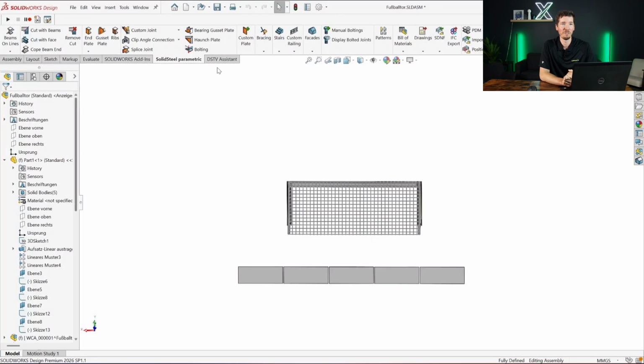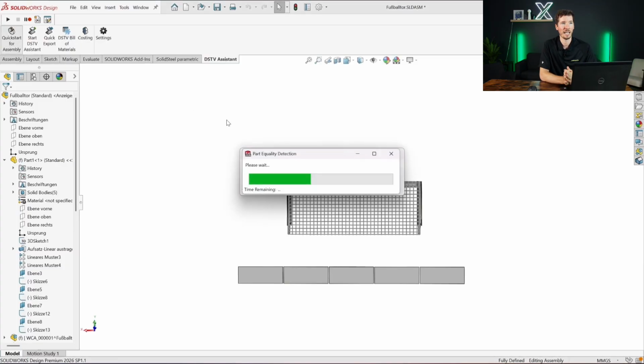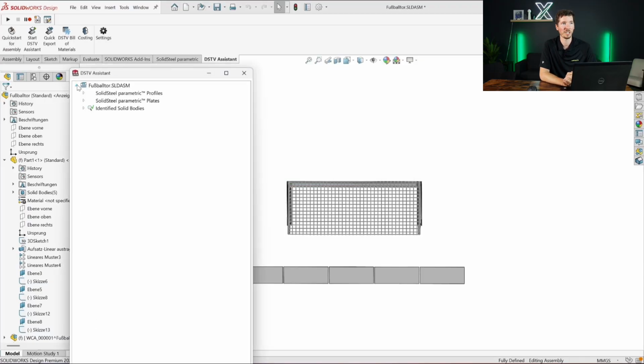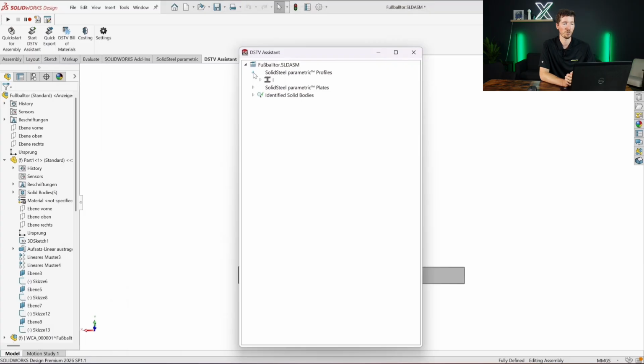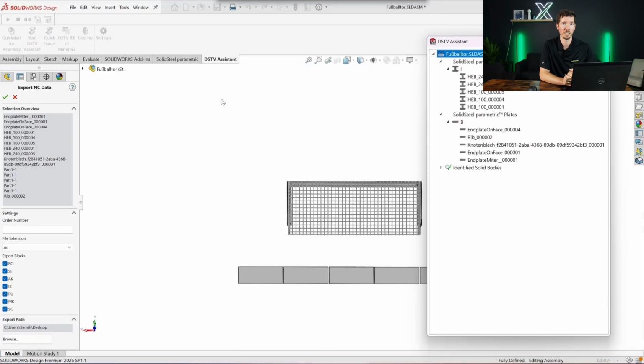So we have a little video here giving us an overview of the quick and easy DSTV workflow to get your NC files. So with our assembly completed, I'm going to start the DSTV analysis process by using the quick start for assembly, which will analyze all the parts within my assembly and classify them according to their specific body types. So I have a category for I-beams, I'll have a category for plates, and this will also work with any imported data such as step files.